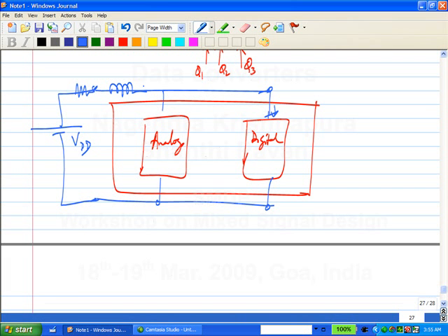Okay, the inductor opposes change in current, so what? So what happens now? Correct. So basically what happens is that the inductor is a short for DC, but will not, as you pointed out, allow sudden changes in current. Correct? But unfortunately the digital blocks draw a lot of current only during transitions. So the current waveform here is very spiky, right? There are huge spikes at every clock transition.